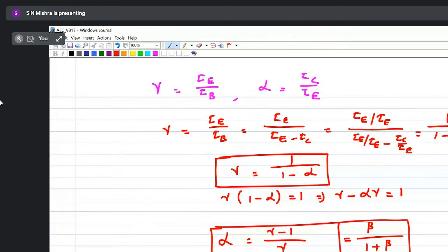This fiber Bragg grating which we have designed is passing lambda 1, lambda 3 and lambda 4, and it is reflecting lambda 2. So the reflected lambda 2 is fed as input to port 2, which will be circulated to port 3 and come out as the dropped wavelength. So with the help of the circulator and fiber Bragg grating, we could drop lambda 2.